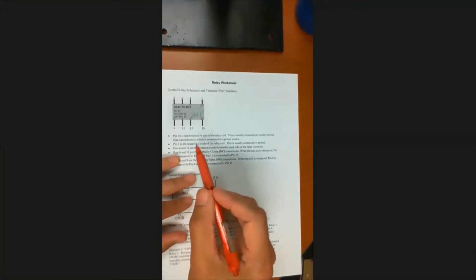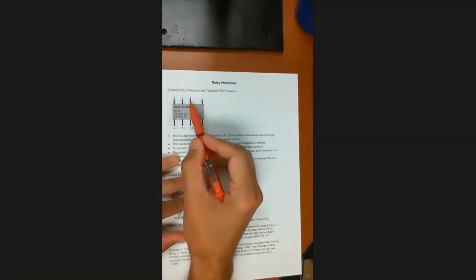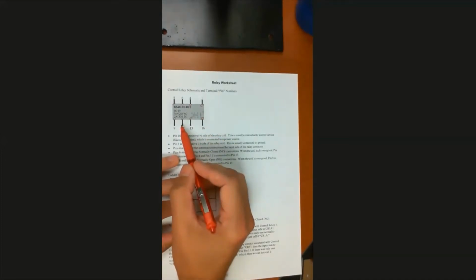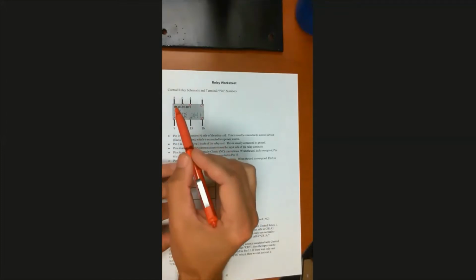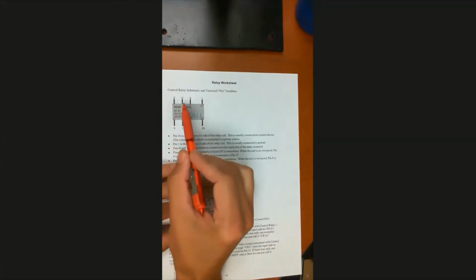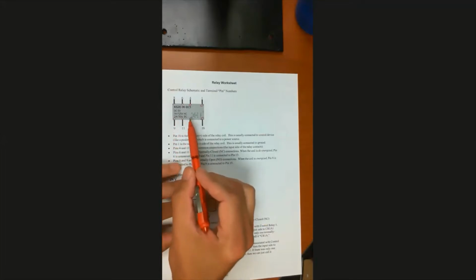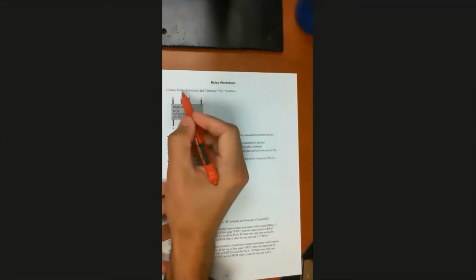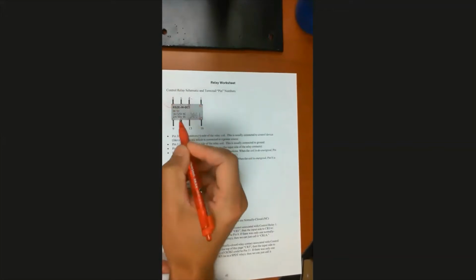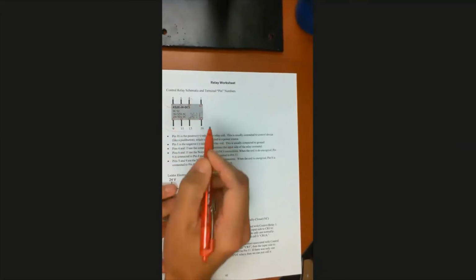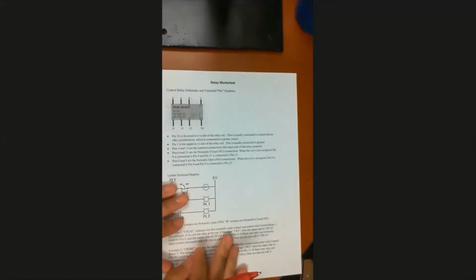And then 6 is the normally closed connection from common pin 4. And pin 11 is the normally closed connection to common pin 13. And pin 8 is the normally open connection from common pin 4, and pin 9 is the normally open connection from common pin 13. All right. So these three represent a single pole double throw switch, and these three represent a single pole double throw switch. And combined, it is a double pole double throw relay.